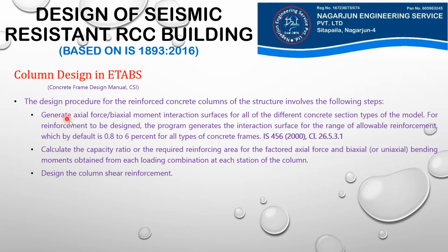First, ETABS generates axial force biaxial moment interaction surfaces for all of the different concrete section types of the model. For reinforcement to be designed, the program generates the interaction surface for the range of allowable reinforcement, which is by default 0.8 to 6% for all types of concrete frames, IS 456-2000. This 0.8 to 6% is based on clause 26.5.3.1 of IS 456 code.